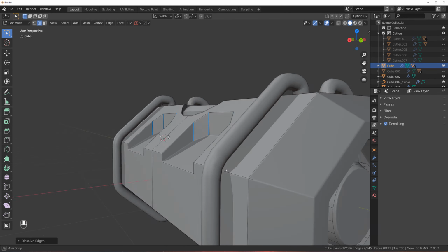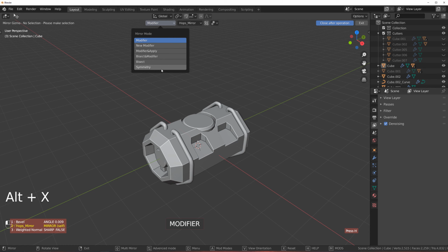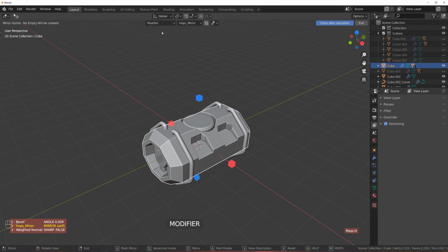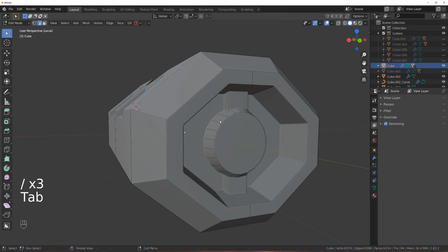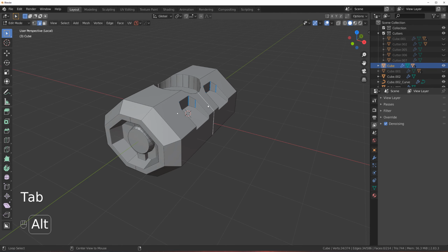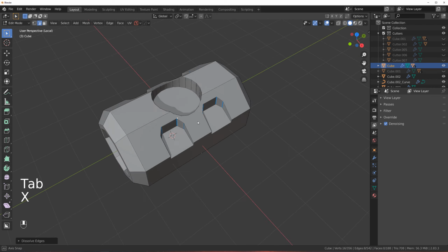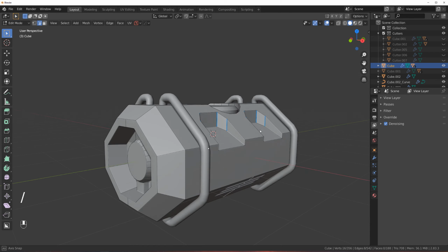And we're gonna probably have to copy to the other side via symmetry. So we could do something like this, symmetry, and come on, D symmetry, and symmetrize it to the other side. So we don't lose these supporting edges here and for the circle. And we're gonna get this edge in the middle, but we can easily remove it, right? But again, you gotta be careful what you're removing so you don't disturb the main shape, right?